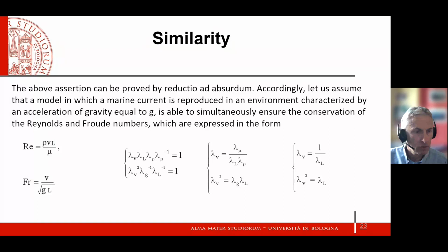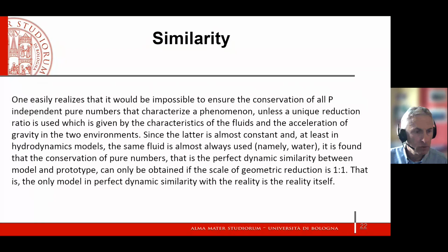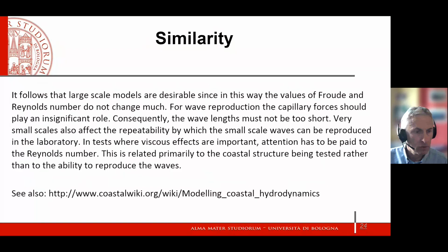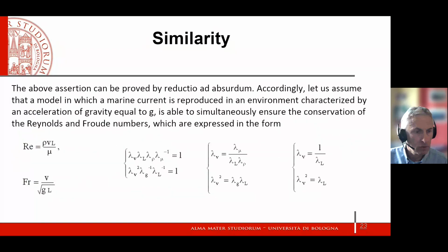So again, it is confirmed what I just stated here. It's confirmed that unless you change the gravity and you change the fluid, it's impossible to preserve both Reynolds and Froude number. So you may say, what is the point here? The point is that a small-scale physical model is not reproducing perfectly the reality. On the other hand,